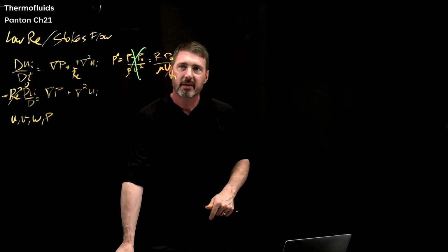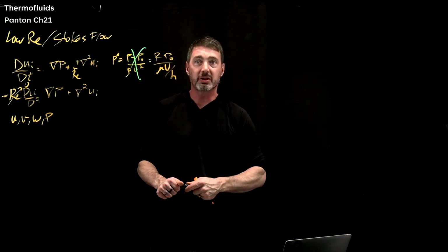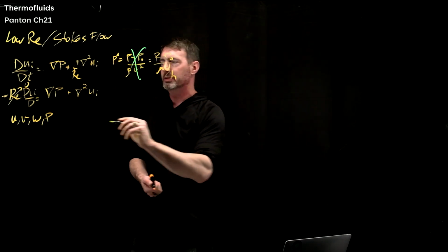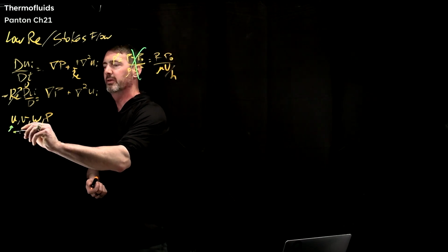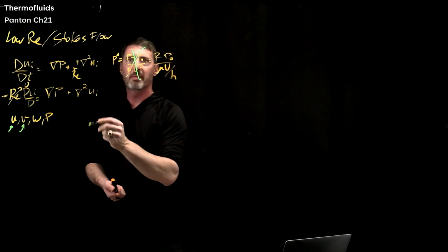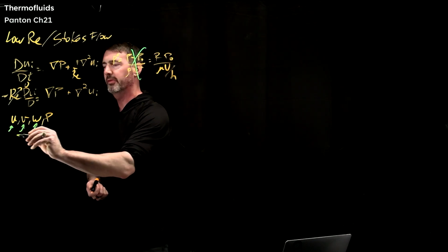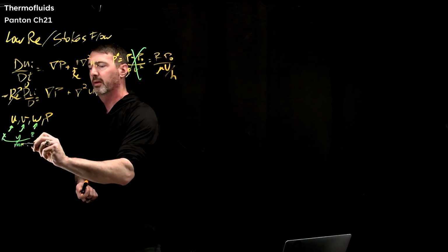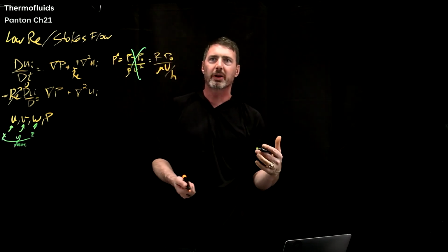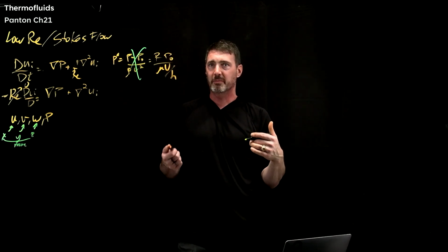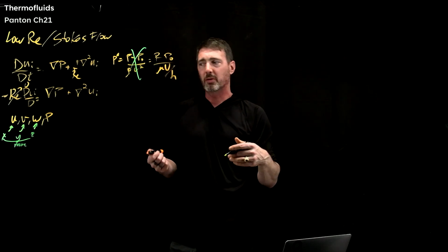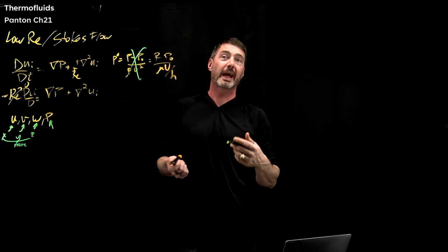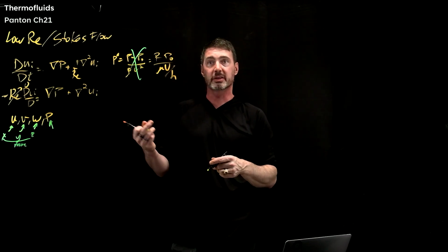This is not really a trick question, but the x momentum equation is the equation for u, y momentum for v, and z momentum for w, so then I only have one more equation. That equation is conservation of mass. So in the incompressible world, conservation of mass is actually solving for pressure. In fact, you can recast conservation of mass into a Laplacian of pressure.